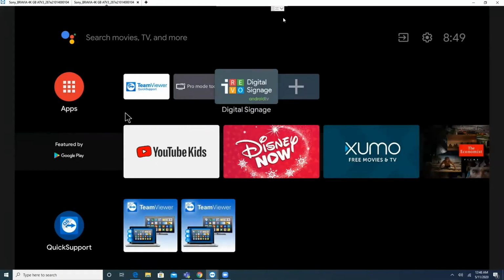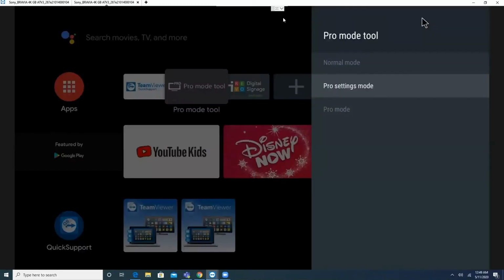I also want to take note of the little things that we did set up that we can actually test. So for example, volume control, I just raised the volume up and it's at 11, so it did default back to 10 when you reboot. Also our banners, for example, right now I'm pressing HDMI 1. When you press HDMI 1, since we disabled them, there's completely no banners, but there's nothing plugged into HDMI, so it'll be a blank screen. As you recall, we left 4 disabled and 3 does have the banners, so all of those are testing out.